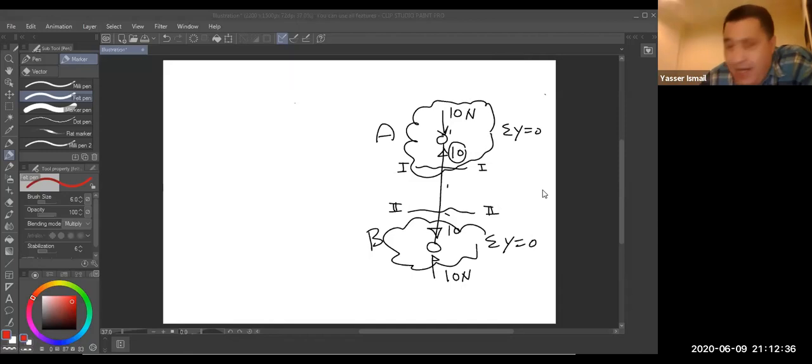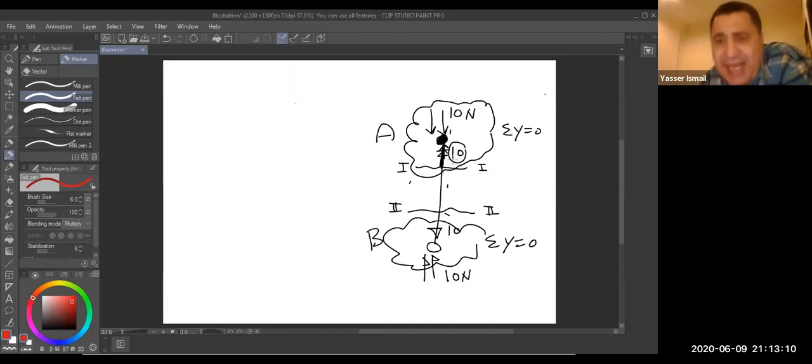Let us see the external force. The external force acts in this direction. See, this is the external force. It makes compression in the member. But the indicator of the forces, okay, makes compression. Okay, how you are going to define it? Put your finger here. Put your finger here in the joint. I am putting my finger here in the joint now. Does this force compress or tension your finger? This compresses. That means the internal force here is compression.